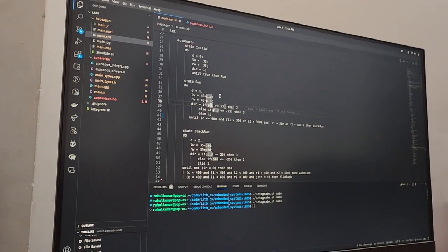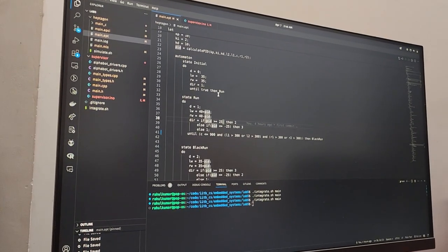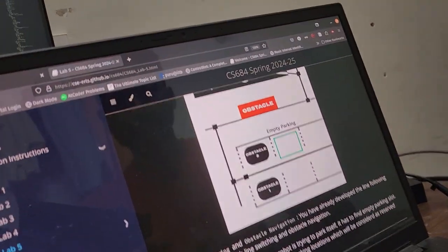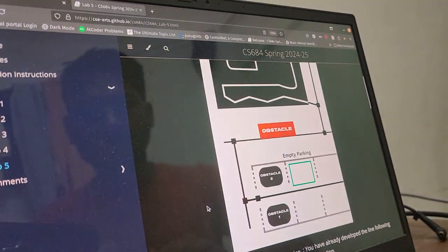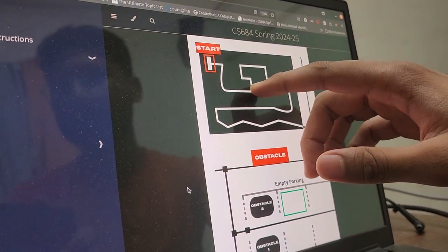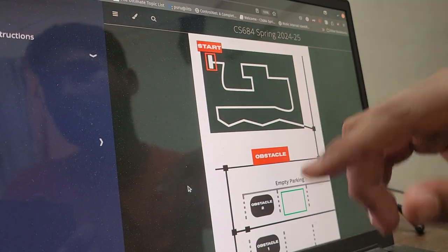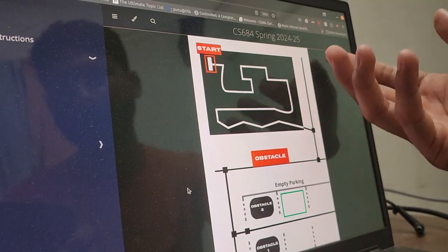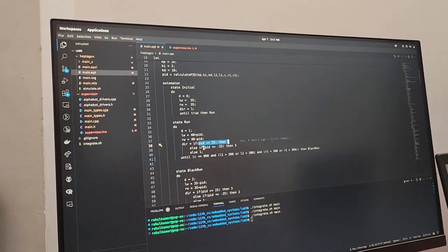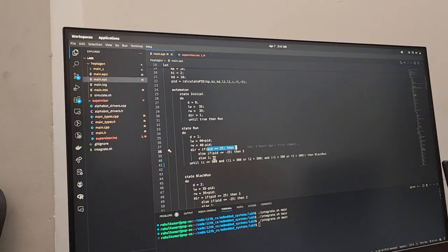Now if you just see on the left side, if there is a white curve, let me show you the part over here. So basically this is the arena. Over here, if on the left side there is a white value, the left sensor will have a higher value, therefore L1 minus R1 will be positive, so PID will be positive. On the positive side, if it goes beyond the threshold, we will do a left turn, similarly a right turn on the other side, else 1.